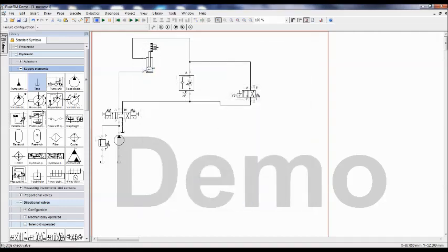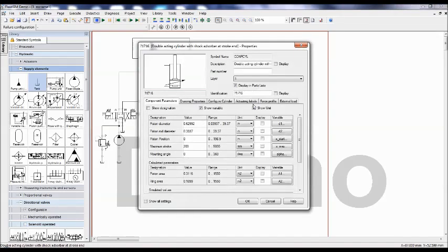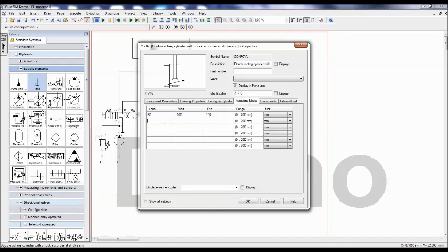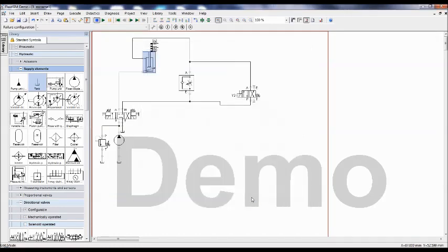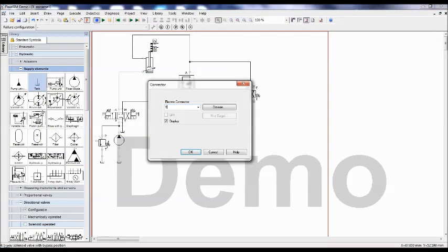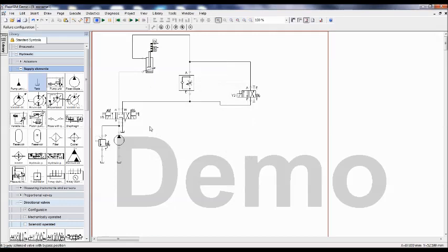Okay, some problem is there. B2 you can take it like 199 because it is not exactly 200 mm. Now it is okay. So B1, B2 sensor is there, right? Now this is the solenoid as per the circuit. This is solenoid Y1. Y1 means upward movement, Y2 means downward movement.